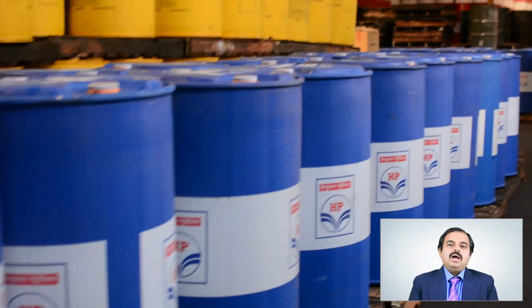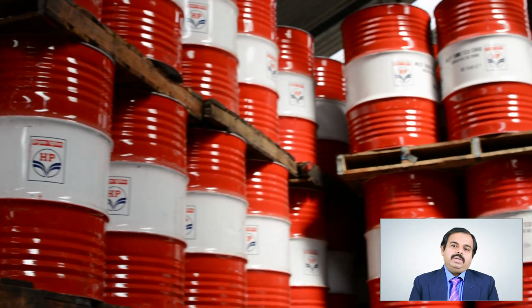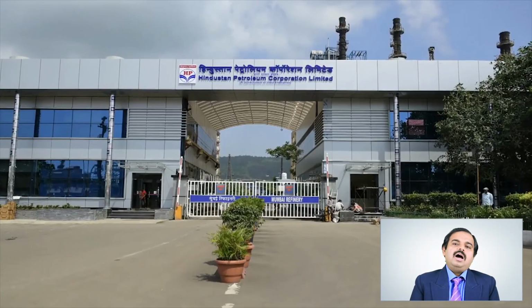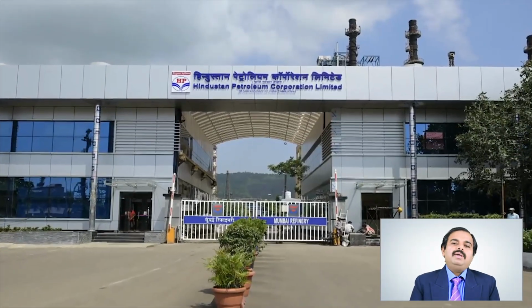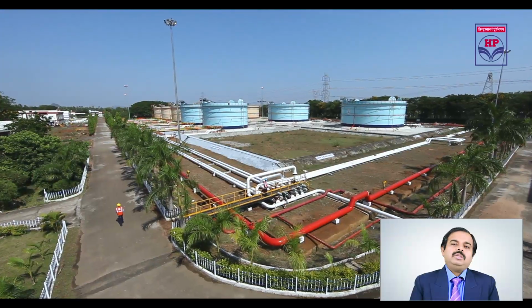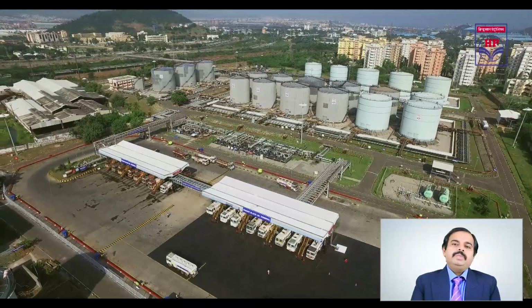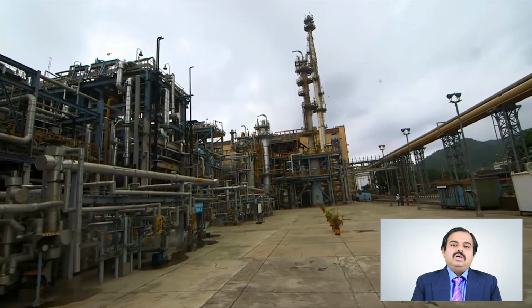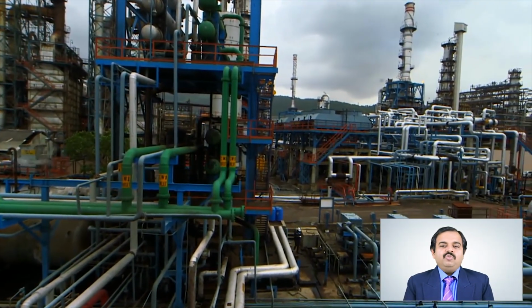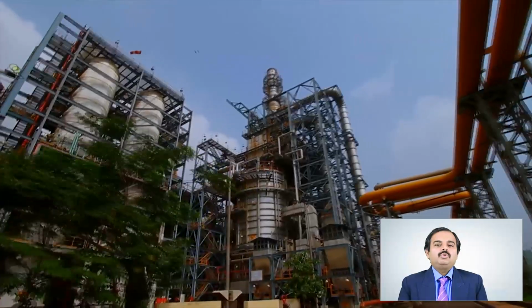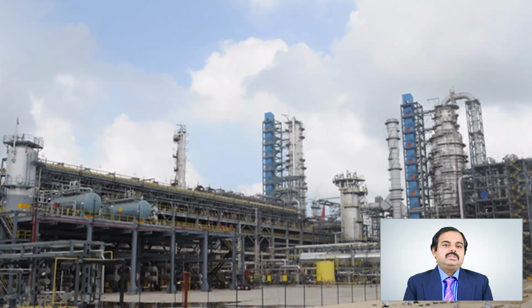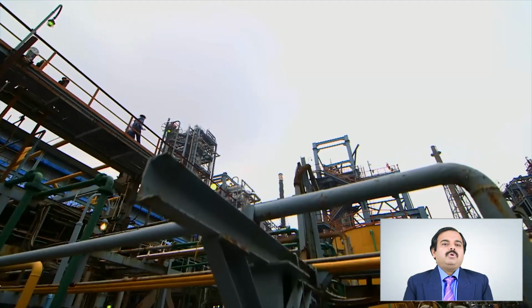The turbine oils are made from deep hydro-finished base oils and select additives. These base oils are made at HPCL Mumbai Lube Refinery, the largest base oil refinery in India. The crude oil comes from the Middle East, which is heated and undergoes fractional distillation under atmospheric conditions. The atmospheric tower bottom, called the reduced crude oil, is then charged into the vacuum tower under vacuum conditions. The distillates are tapped off.